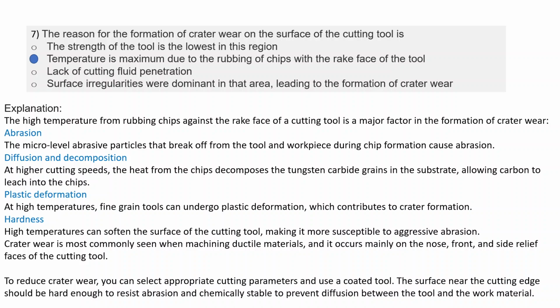Then diffusion and decomposition: at higher cutting speeds, the heat from the chips decomposes the tungsten carbide grains in the substrate, allowing carbon to leach into the chips. In case of plastic deformation, at high temperature, fine-grained tools can undergo plastic deformation, which contributes to crater formation.